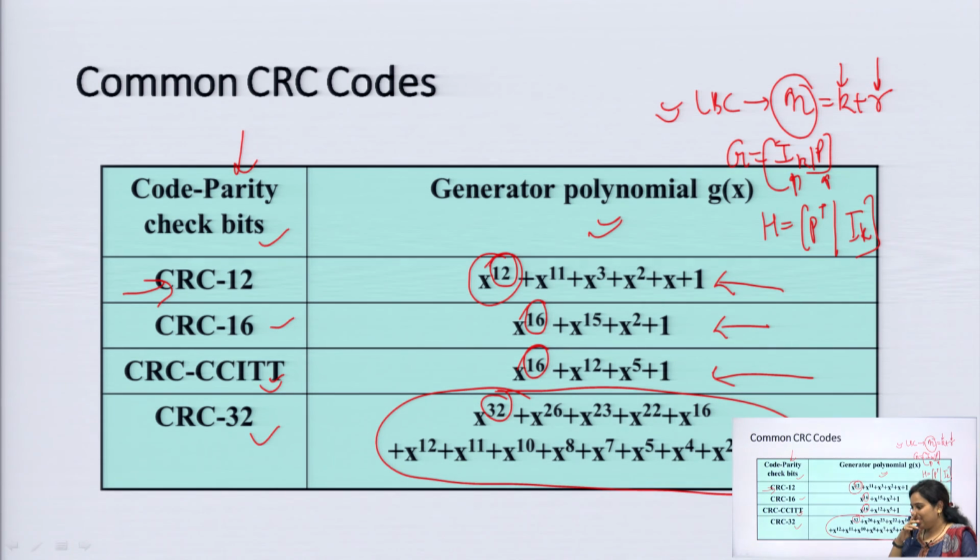Then we have seen the cyclic codes. In case of cyclic codes, we have used the concept of shift registers. Whenever information is incoming, any message bit will be added to this particular shift register, then the data will be shifted into the next registers and forwarded in that sequence. Whatever data is generated in the next code is again a valid code word. The shifted code word is another new valid code word. So, this is about the cyclic codes.